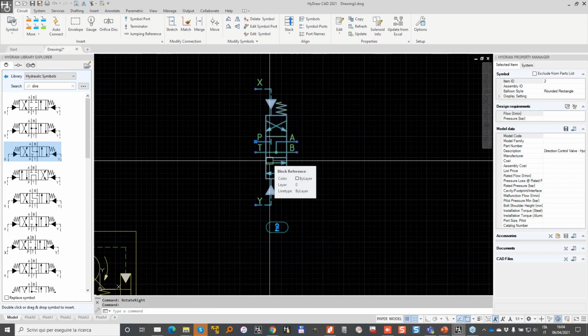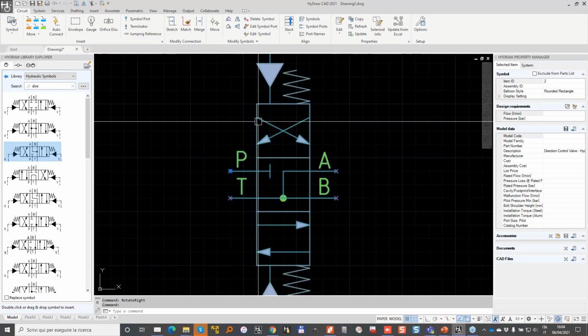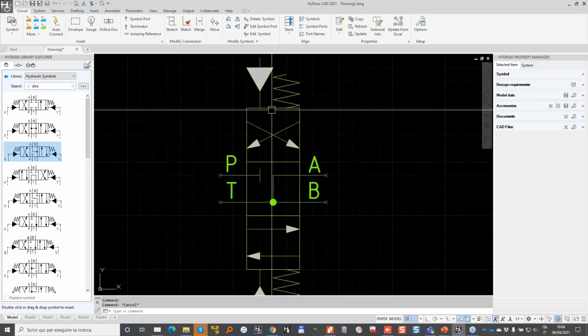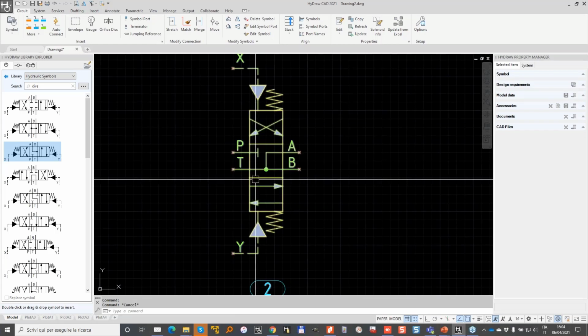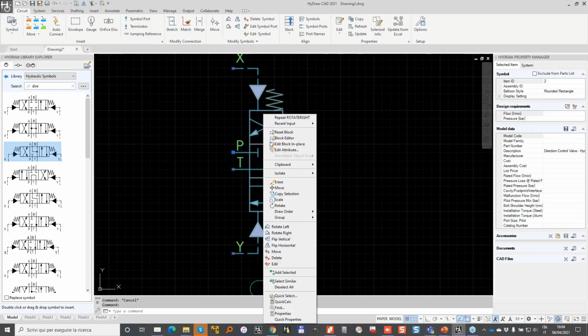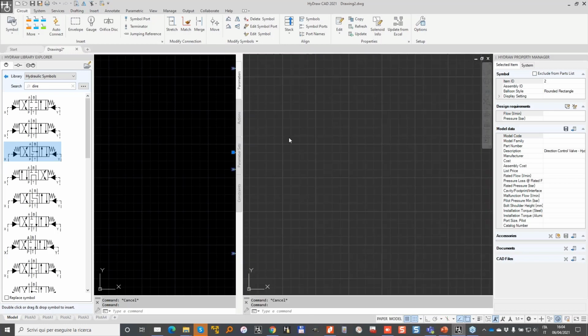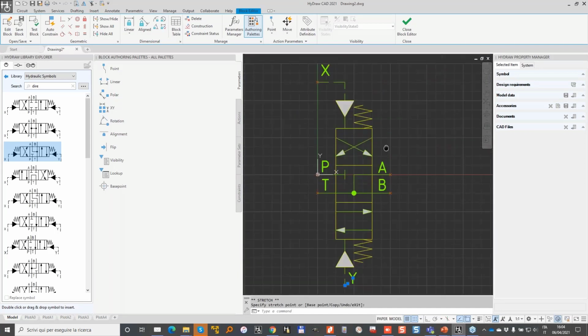If you need to do a modification, now I really want to change a bit, because although this symbol is ISO compliant, I want to show that this symbol can have unlimited positions in all the Y directions. Usually there is a symbol that we use in the ISO 1219. So I right click, block editor, and enter my editor mode. First I want to remove this small segment. This change will apply only to this diagram that I'm making. So my symbol is made this way.